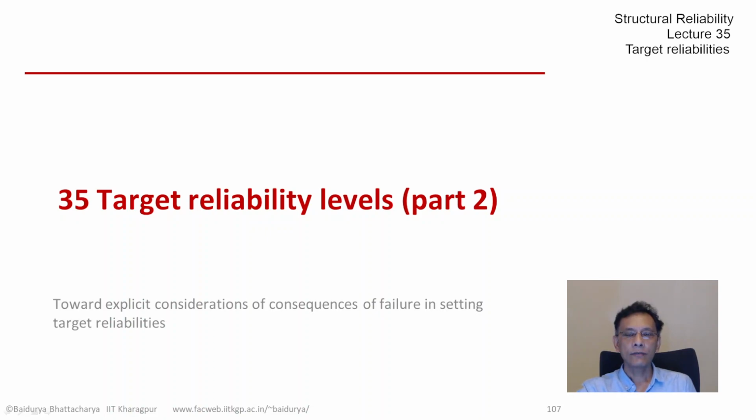But they suffer from a couple of problems, as we discussed. The traditional design codes which were used for this calibration exercise have evolved over decades of successful use, and they have imbibed various experiences and wisdoms from the practitioners. So the implicit reliabilities are not necessarily uniform for the same limit states across different load combinations and different materials, and using those same implicit reliabilities in the new design codes has the potential of perpetuating a suboptimal design.